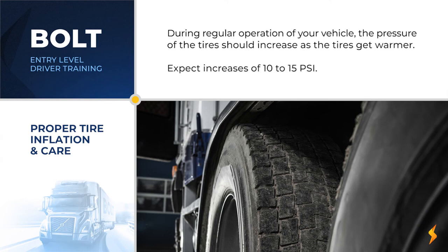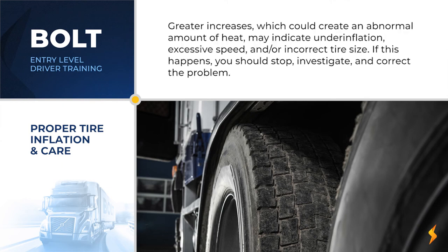During regular operation of your vehicle, the pressure of the tires should increase as the tires get warmer. Expect increases of 10 to 15 psi. Greater increases, which can create an abnormal amount of heat, may indicate underinflation, excessive speed, and/or incorrect tire size. If this happens, you should stop, investigate, and correct the problem.